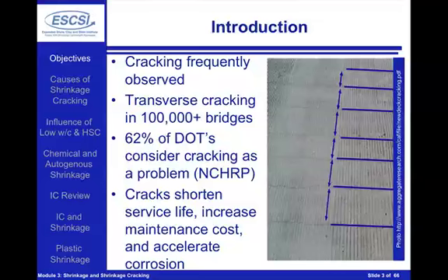The reason is cracks can shorten service life, they can increase the maintenance cost, and they're going to accelerate corrosion, which has the potential to reduce the service life, impacting sustainability and the life cycle costs associated with that part of the infrastructure. In addition, in many cases, cracks are unsightly. What we're talking about here is not eliminating all cracks in concrete structures, just the cracks that can be avoided, such as thermal cracking or, especially, shrinkage and water-induced cracking in these systems.